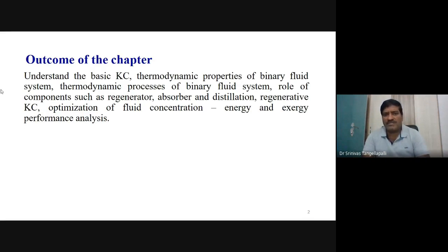So, to solve the process and the entire Kalina cycle system, the solving of thermodynamic properties is slightly different compared to the single fluid system because of an additional property. One extra property is coming here, which is the concentration. In addition to the pressure and temperature, concentration also we have to deal with. That's why the thermodynamic properties are especially focused on in this presentation.